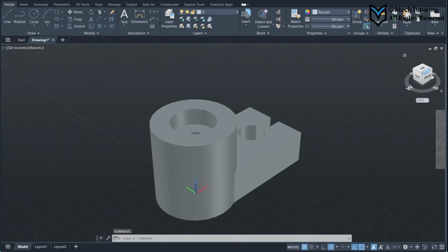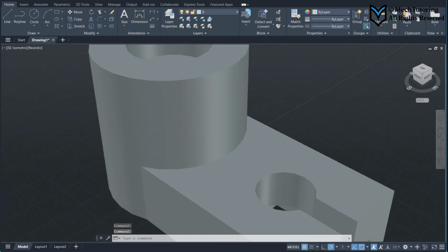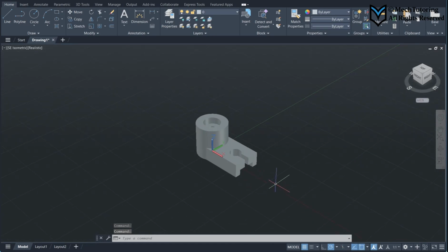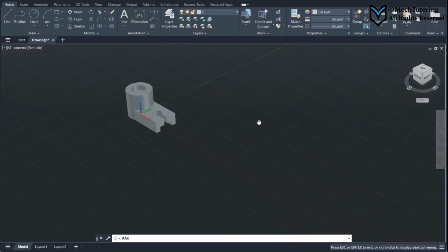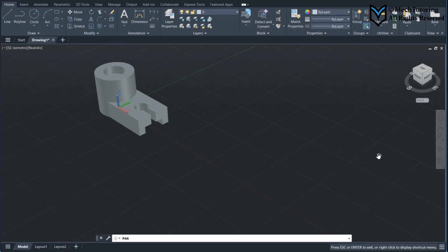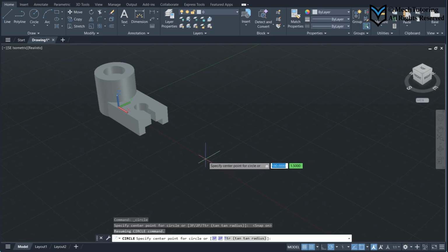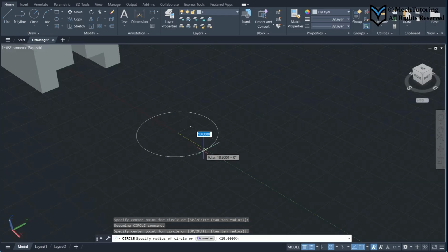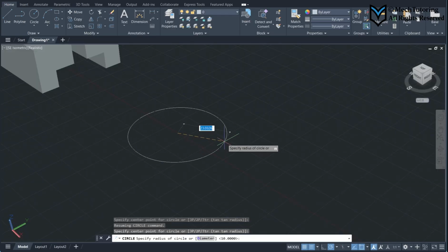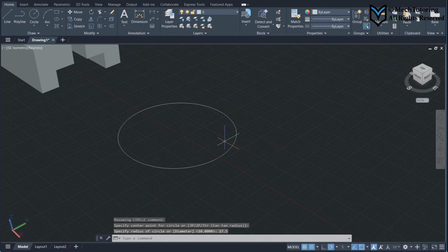So I'm going to go back to the 3D and I'm going to create the wedge on the side over here. To create the wedge, again the same rule. You're going to go and you can turn on this snap, and pan is off. Then select this edge, zoom in, select this edge here, okay, and draw the cylinder again, 27.5 radius.